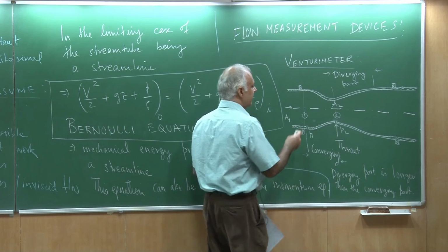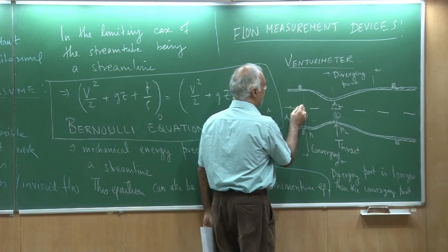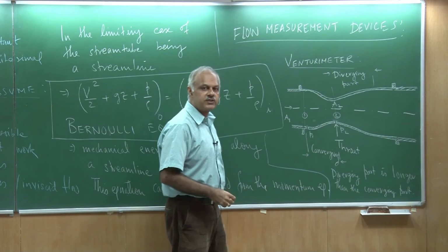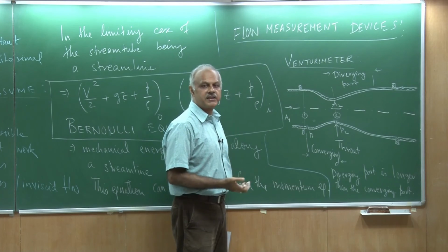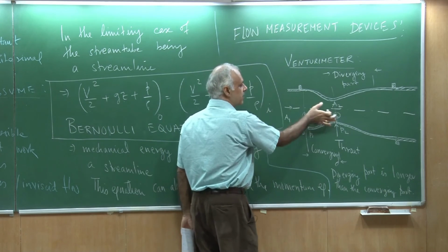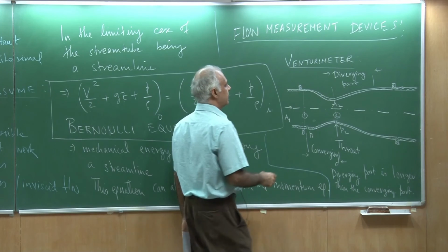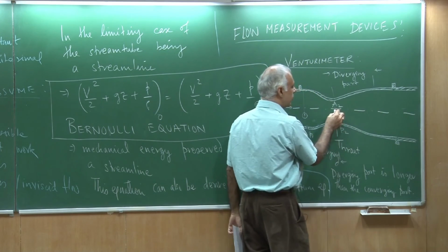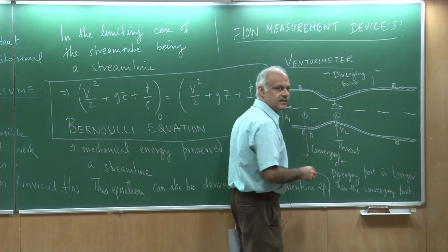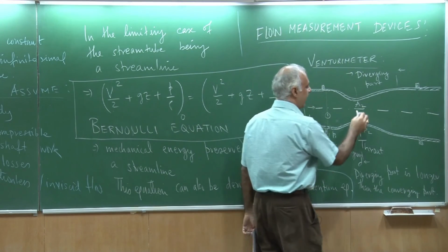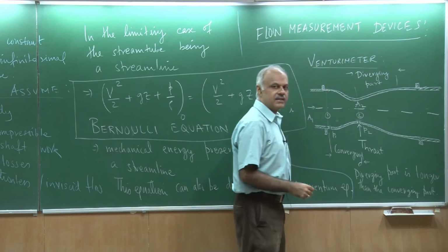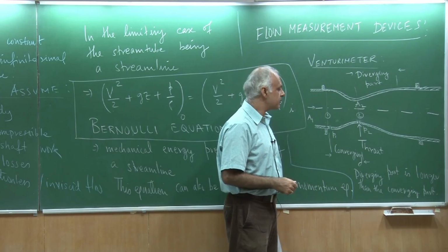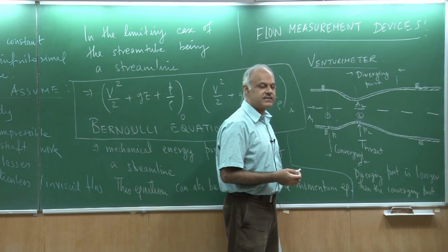What is happening here is I go from a high pressure to low pressure. So, in this part the pressure is reducing and we call it a favorable pressure gradient. The flow is moving towards low pressure. Okay. On the other hand, my pressure recovers here. So, I had low pressure here because it is a high speed moving fluid, and then in the divergent section the fluid again retains its old speed. Okay. It becomes slower and then the pressure increases.